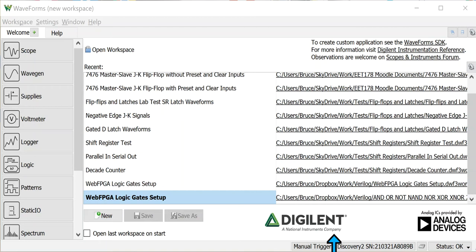A pattern generator differs in that the signals that you create are for the digital logic environment. So you're creating a signal to apply to the input of a logic IC. Perhaps you want to exercise an AND gate, and you want to create those signals to do that and see how they work in the learning environment. That's what you use a pattern generator for. Not a very common tool. As I said, very, very helpful in teaching people about digital logic.